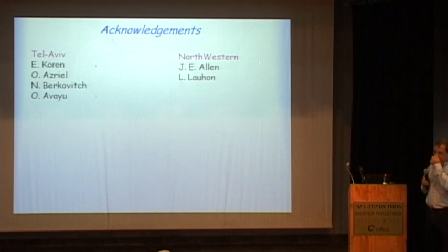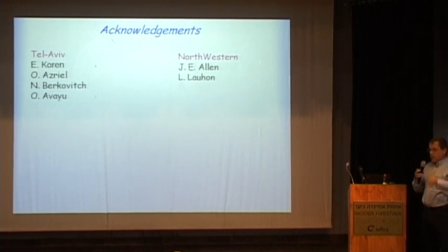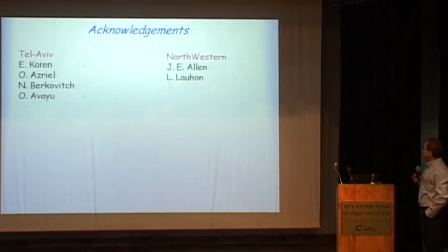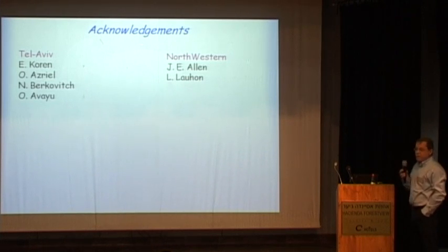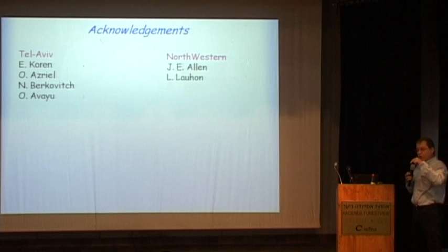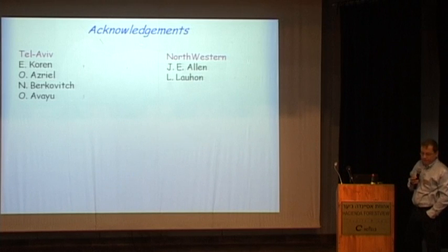Were the nanowires grown by co-depositing silicon and phosphine, or were they first grown with silicon and then doped with phosphine? Together. Then why is it appropriate to talk about the diffusion coefficient? In principle, it should all have been uniform. No, but the silicon goes only through the top, through the gold catalyst, and the dopants go through the sides. How is that known? This is by the method. I'm not an expert in this, but this is the principle of the VLS method. There is a eutectic reaction between the gold and the silicon, so the silicon grows only like a mushroom from the top.